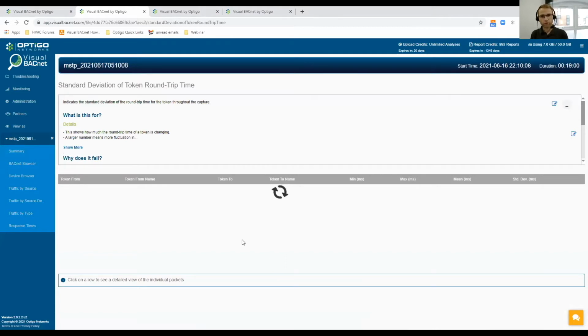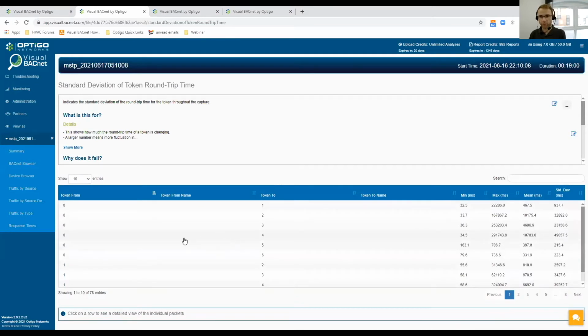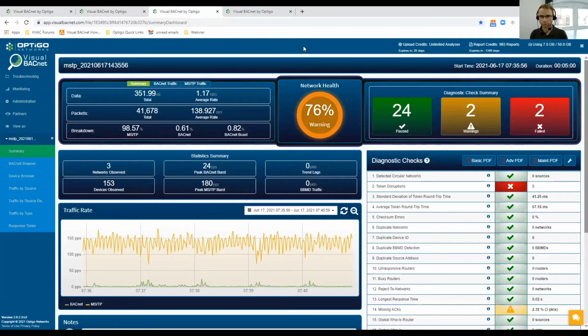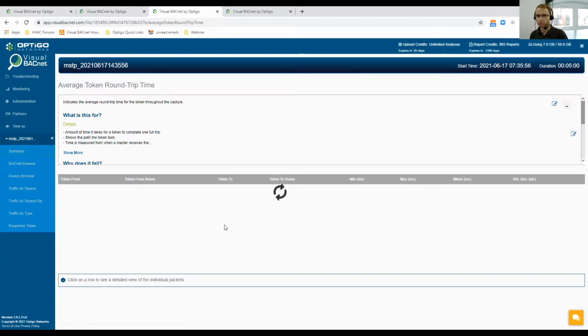And once we got those communicating correctly and reliably, we were then able to break it a little bit further down. Let's bring another 3 or 4 devices on, see what happens, and just keep moving through the network, isolating chunks, running a small capture, maybe 5 or even 2 minutes perhaps, seeing what data we get back. And then eventually we started to narrow down. It became clear that there were a couple of pump sets, which every time we connected these, all the pumps were bringing it down. Again, fortunately, being as we were in a small boiler house, we were able to throw a flying lead from the panel out to these pump sets and just test them in isolation to see which one of these devices was giving us the problems.